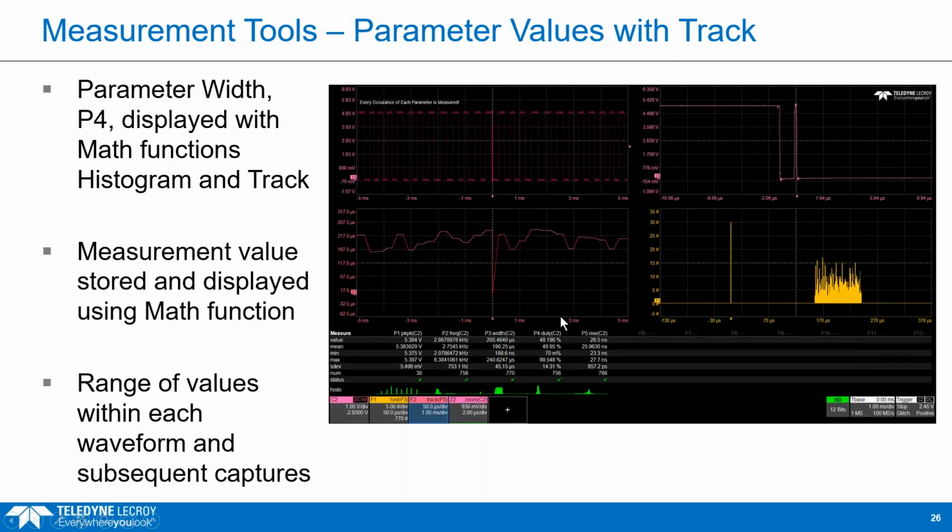I'm thinking too, what would be really good too is to use these rise time measurements and back to the front of the presentation, the coffee break. It would be interesting to look at the statistics table of the zoom of the edges from a waveform acquired at very low levels, very low amplitudes, when it should have been using the full dynamic range of the scope. And you compare those rise time or fall time measurements, that would be a good thing to show you too, but I know I have to, I might just still show you at the end here.